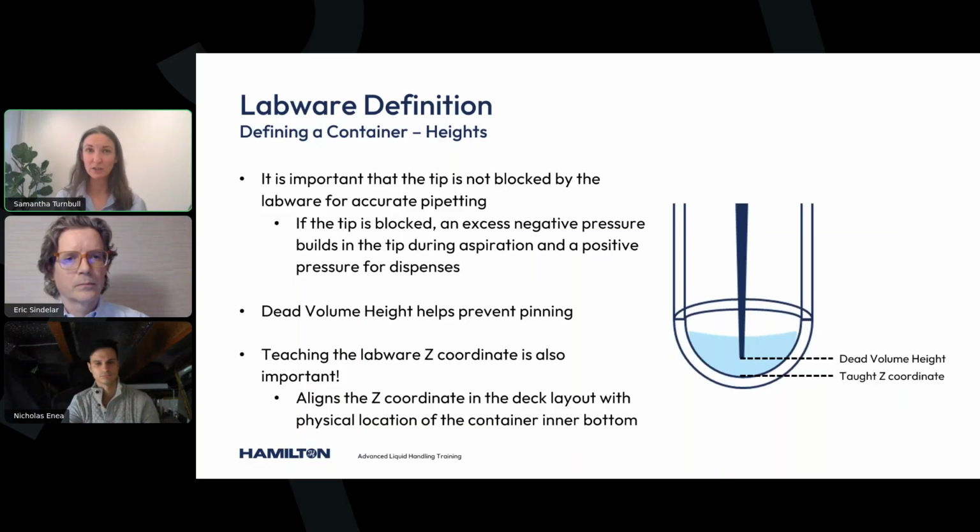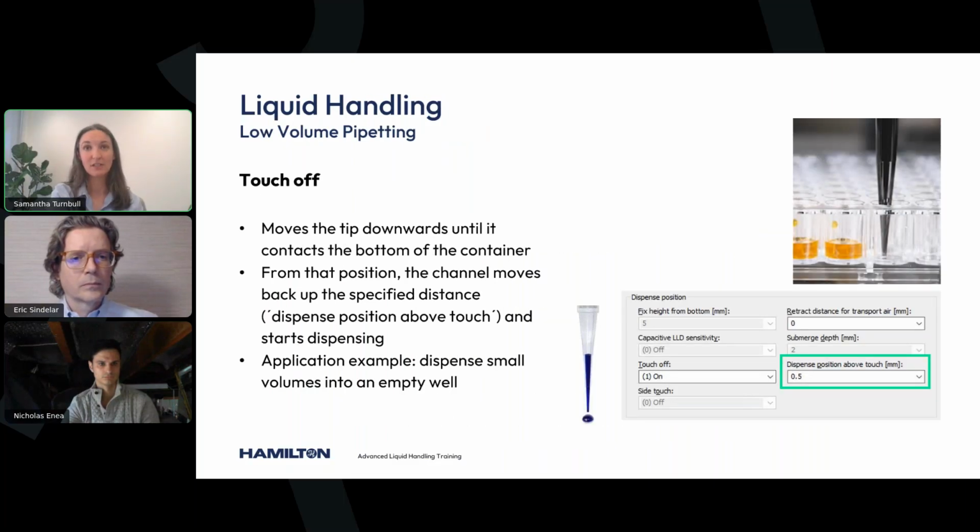It's best to leave a small gap here to allow free flow of liquid in and out of the tip at all times. Now, once you have a good, accurate labware definition, we also have some other modes you can use. One is a touch off. This allows our tip to move downward, detect the bottom of the well, and then retract a specified distance before starting the dispense. This does not excuse a bad labware definition, but it is very helpful when dispensing